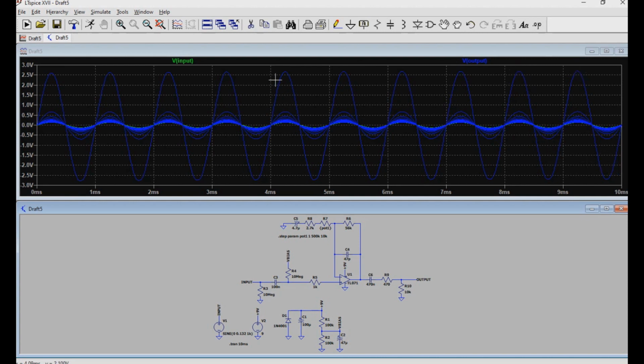But one thing you also notice when looking at this sine wave is this is a clean boost. There's no flattening of the top of this curve right here. So there's no clipping of the rails, as they say. Well, what would that look like? Remember, I'm using a sine wave of 132 millivolts, which is like a very hard single string hit on moderate pickups. But let's do something that's more like a power chord on active high gain pickups.